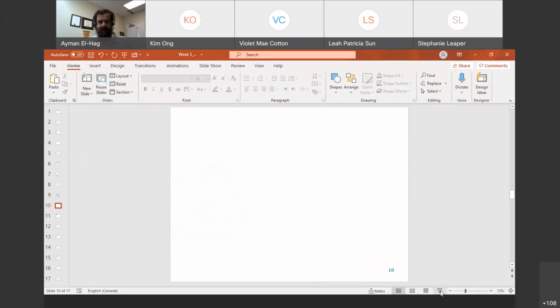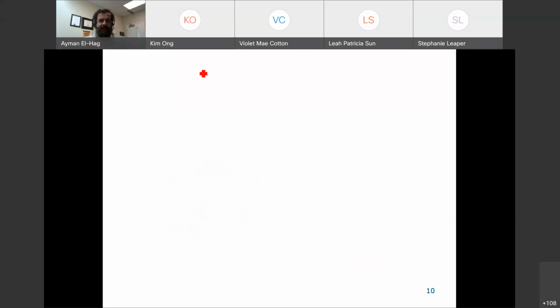We are used to it. So let me write down the two equations I just had. The first equation is 7V1 minus 2V2 equal to 60. The second equation is minus 2V1 plus 5V2 equal to 10. So basically what we can do is represent one variable in terms of the other.